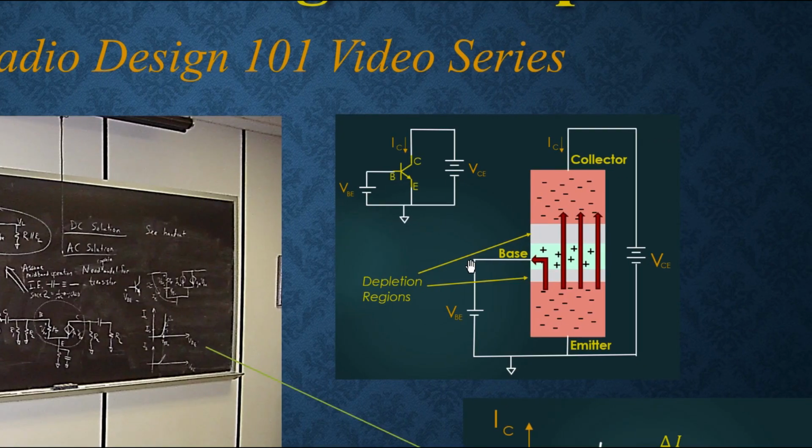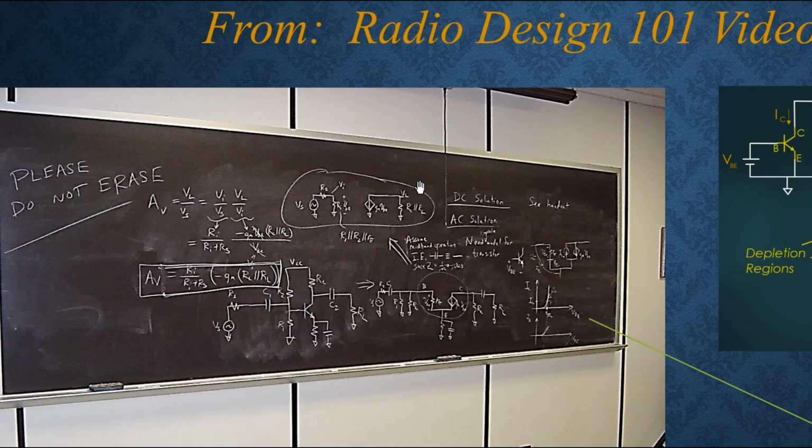This is a transistor, and all you have to know here is that if you put a voltage between the base and the emitter, then if there's a voltage between the collector and the emitter, you get current flow. And as you change the voltage on the base relative to the emitter, it changes the current flow. And that's the basis of what's going on in this amplifier analysis. Vary the base emitter voltage, that varies the collector current. Oh wait, how does that create an output voltage?